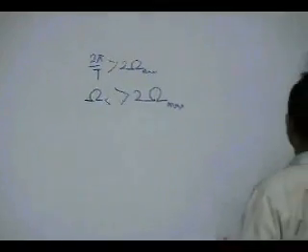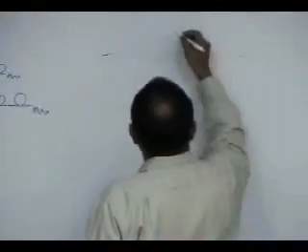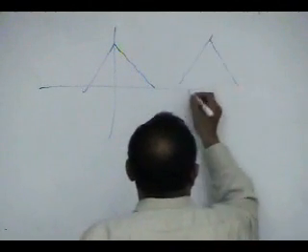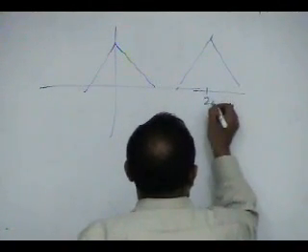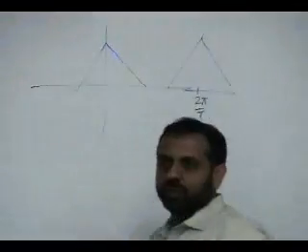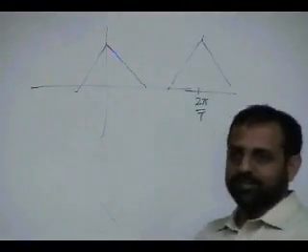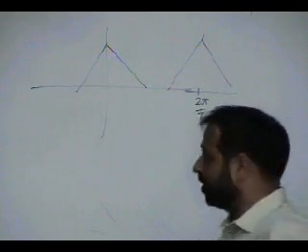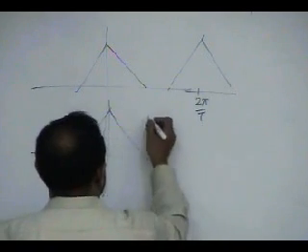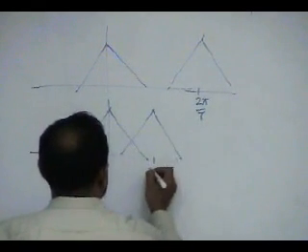What is aliasing? Maybe easy to see it here, that this is fine if you are sampling fast enough such that your 2 pi over T is greater than 2 omega max. You are safe. If not, then what will happen? You will alias, right?